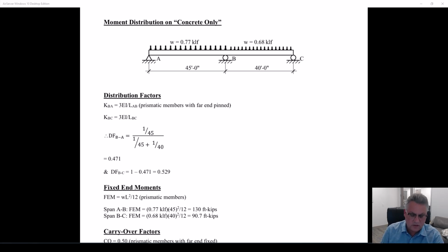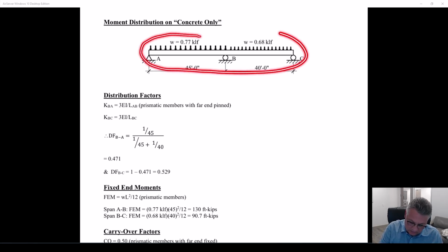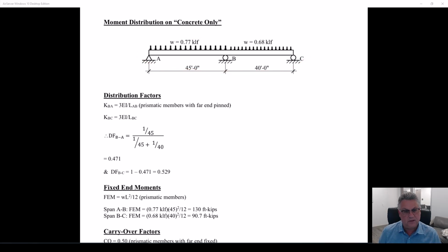We have fictitiously put the upward balance load on the concrete and ignored the fact that the concrete is doing the same thing back to the tendon. So we're only including about half, almost exactly half, of what is happening in pre-stressed concrete. So in this pre-stressed concrete beam, the concrete only thinks that these are the loads on it. Not statically correct, but very useful for calculating the stresses in the concrete.